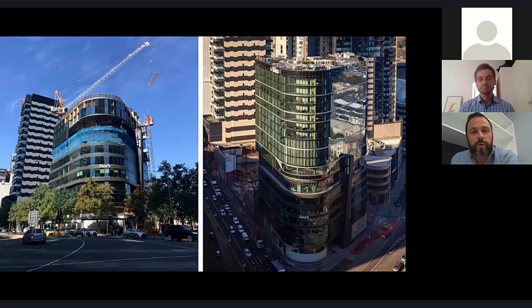But because we only had one crane, we had to supplement that with what we call a spider crane or a crawler crane, which is very small. And on the image on the left, what you can see is on the back corner, we're lifting up CLT to half of the structure, and we're installing facade on the other side, where we've got a small crane just manoeuvring around the active deck and dropping curtain wall panels over the edge. So it worked really efficiently. It's probably the most efficient component of the project, but it's something that needs to be really considered during the design, and how that's connected and how that works in with the timber component.